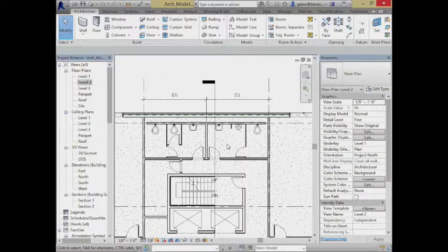And by putting things into these little mechanical chases, it not only makes it easier to route everything, it actually makes it easier to service anything, because if there is some sort of problem with the piping or the valves or just something that needs to be changed later, rather than having to tear into the tile and tear into the wall and mess all that up, these things are often set up so this top piece right there can be removed temporarily, and you can still get access to everything. So there's a functional reason for doing that too. But we often see things as more this double wall construction.